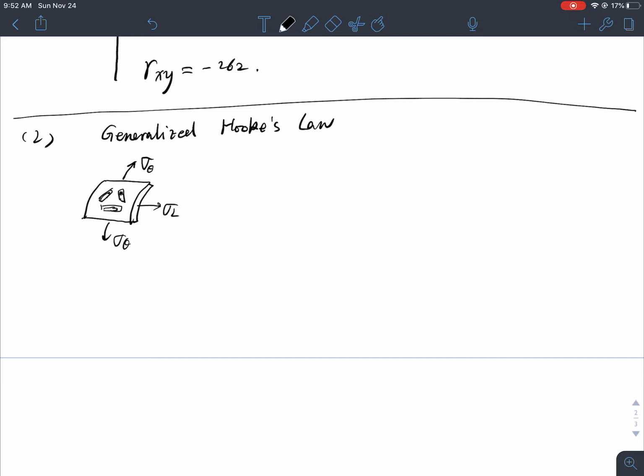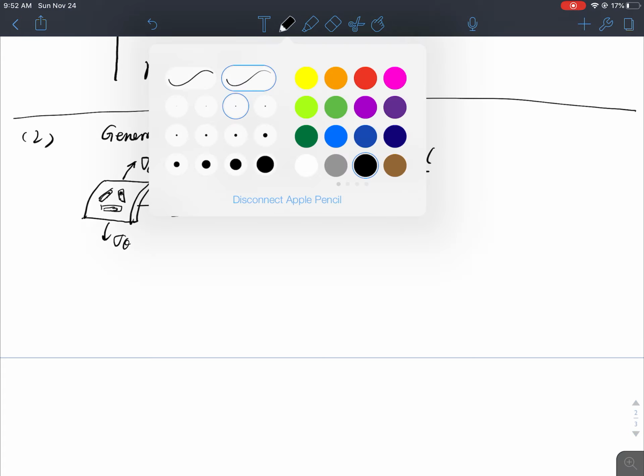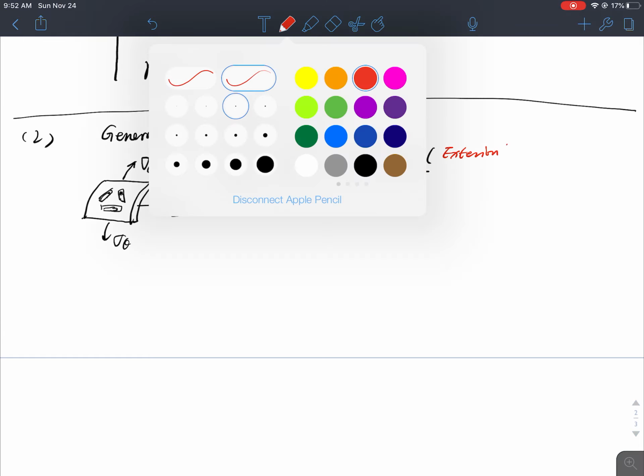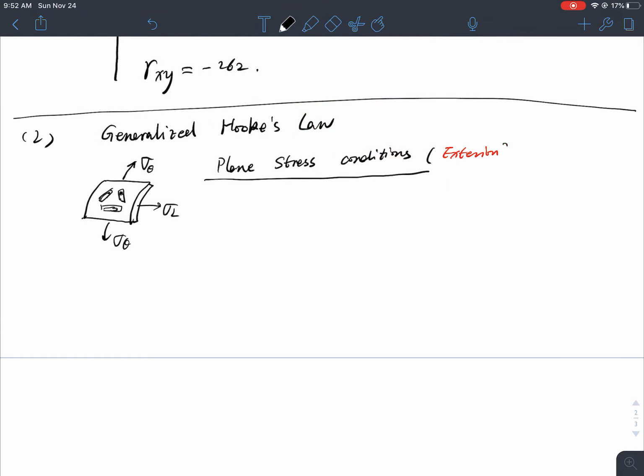So we look at it and we realize that it is basically a plane stress condition. A plane stress condition. Okay, and be careful though. I have to say this has to be on the exterior. Okay? Because at the interior, I do have a pressure to consider.